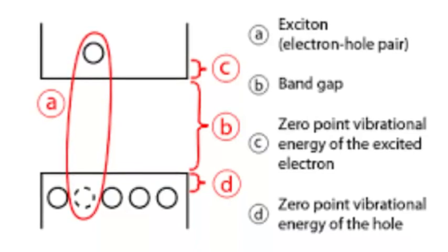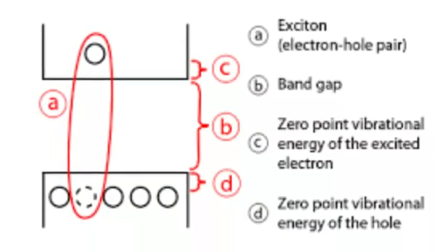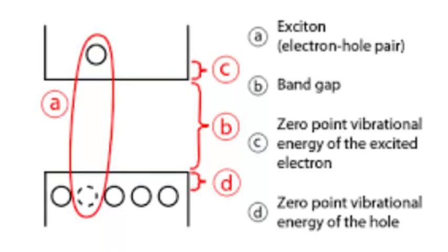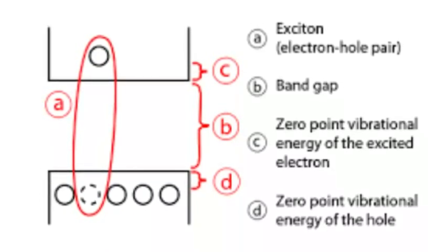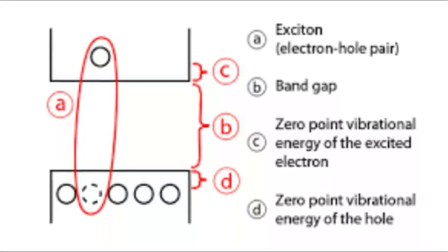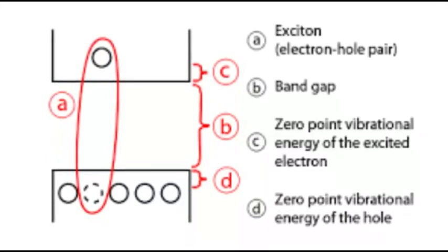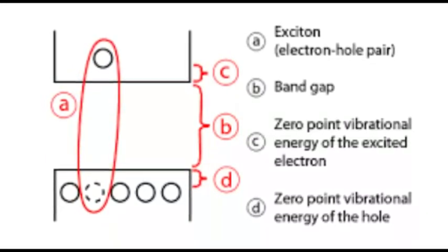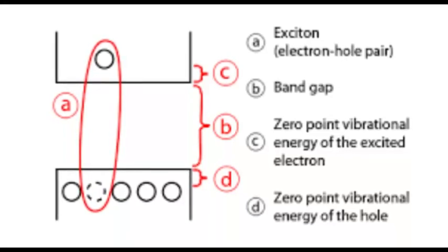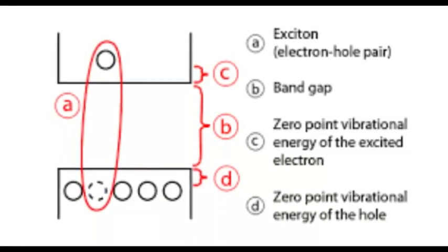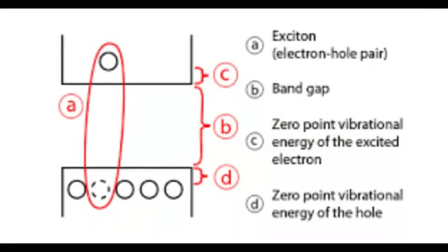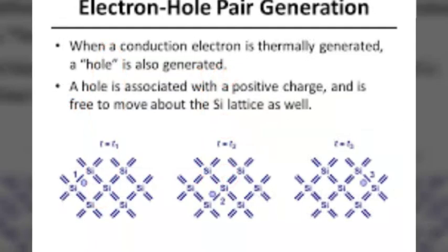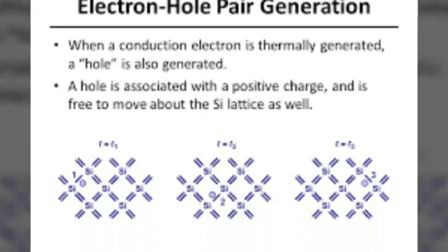As the temperature is raised, some of the valence electrons acquire sufficient energy to enter into the conduction band and thus become free electrons under the influence of an electric field. These free electrons will constitute electric current. It may be noted that each time a valence electron enters into the conduction band, a hole is created in the valence band. These holes also contribute to the current.